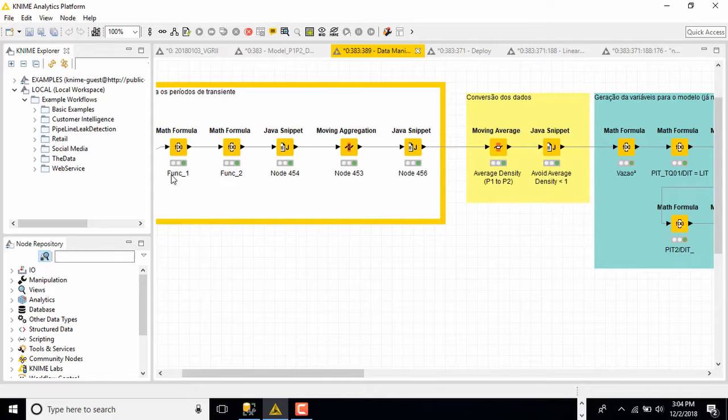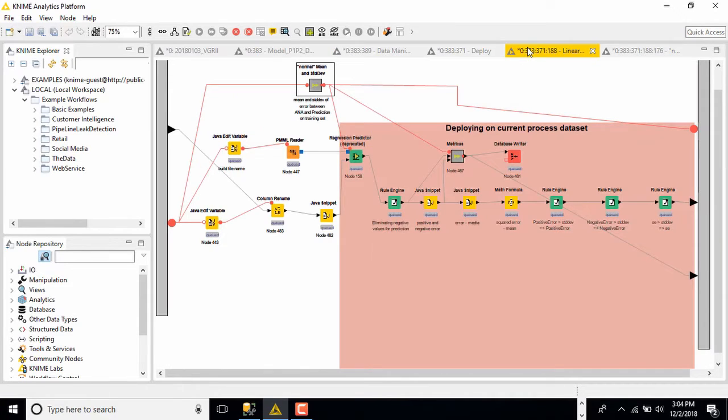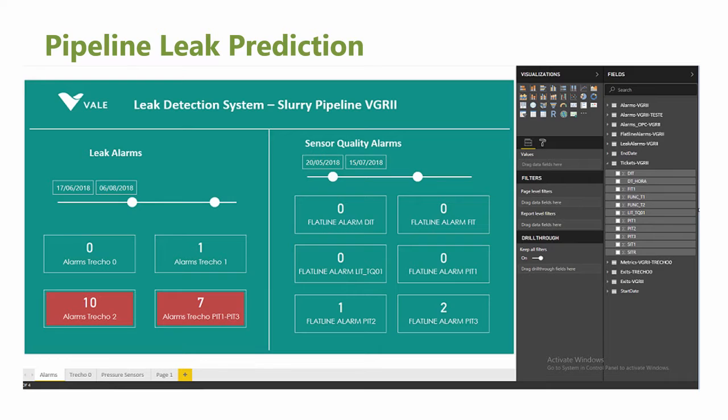The anomalies in the received data points seen over a certain period of time are analyzed to identify a concern for the leak. That transient duration over a defined range, where anomalies are seen and seem to be stable, indicates a possible leak. On such data points, alarms are sent to an OPC server and visualized to take control actions such as calling for a manual inspection.